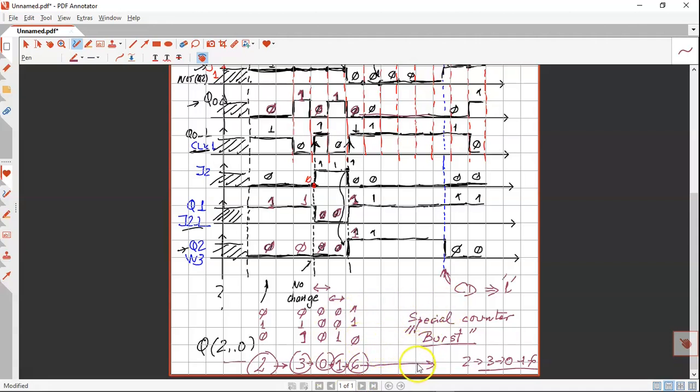But in the final gate level simulation, things went differently, because we were zooming in on one of these transitions, and in between we got different codes. I remember that between the 1 and the 6 we were able to see the 0 and the 4.